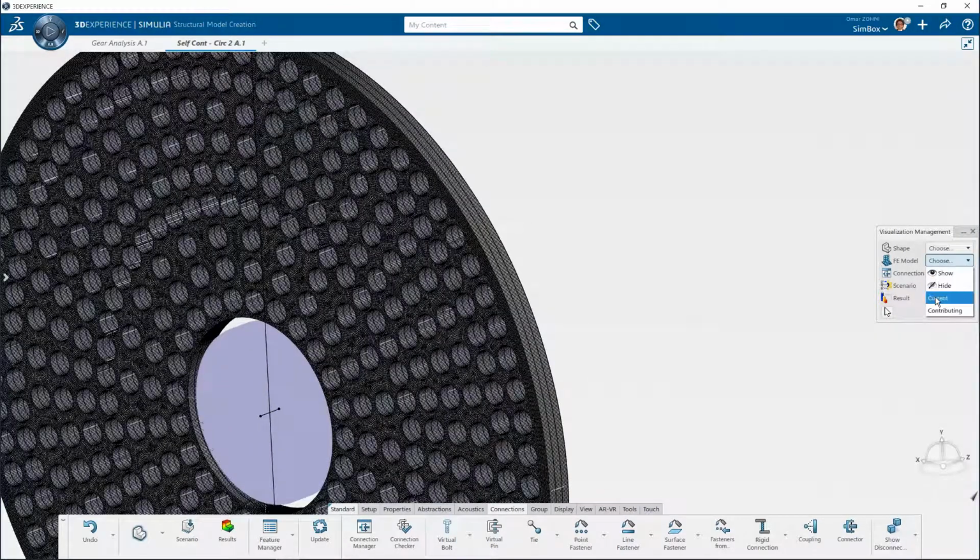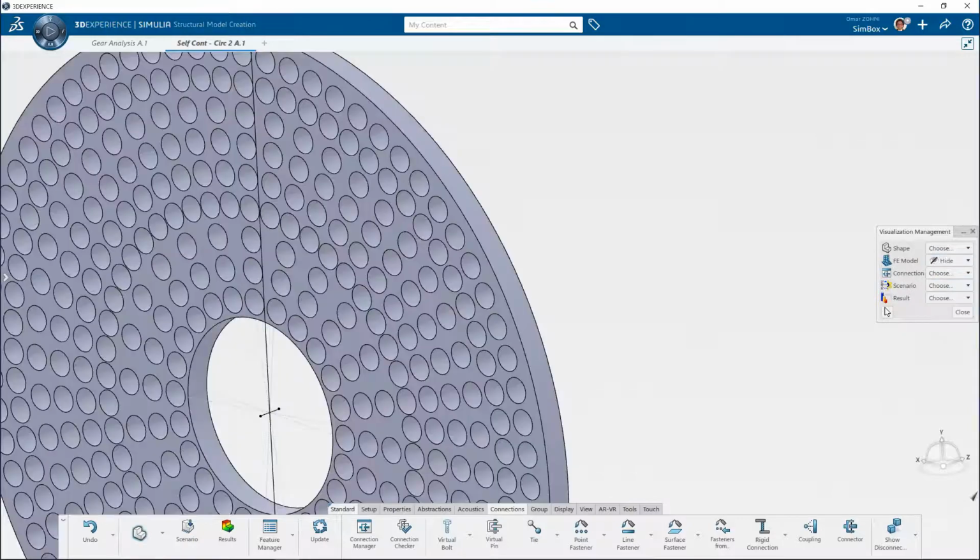If you guys don't know, in general, when you're using brick elements, it's a little bit easier numerically on the solver to reach convergence. So that's something that we didn't have in SolidWorks. We were forced to use TETs. A TET mesh you could throw in any geometry, but having the ability to apply a brick mesh is really, really nice.